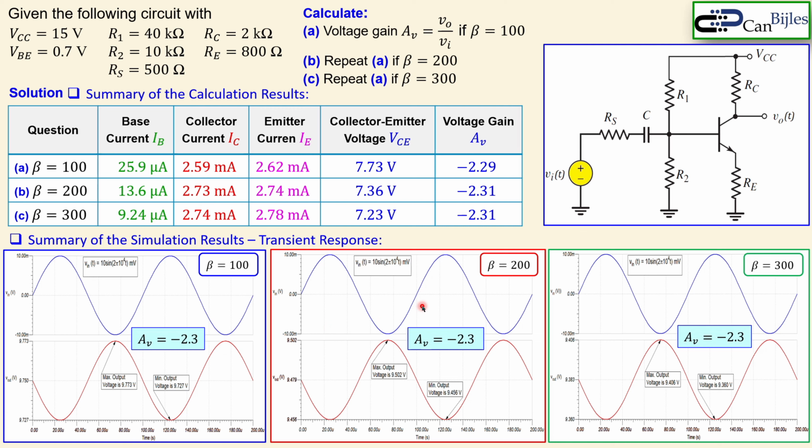So we have seen in this example, also with emitter resistors, how this circuit can use this resistor as a stabilizing component in our voltage gain. If you decrease this resistor, for example, make it 500 or 400 or 200, of course the stability effect will reduce. So the larger this value, the more effect it has on the stability. Of course, if you make it larger, you will also lose gain. So there is an optimum, actually a sort of a fight between the stability and the amount of gain you can achieve with this circuit.